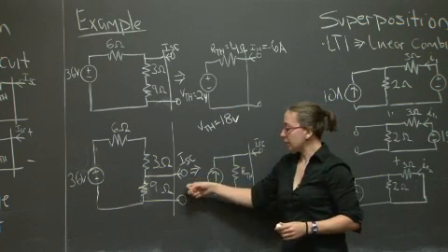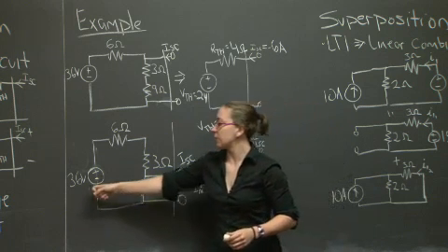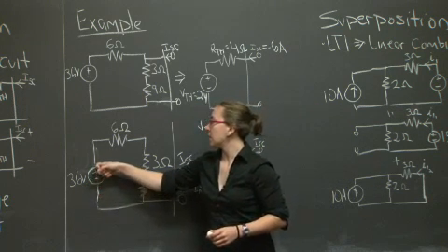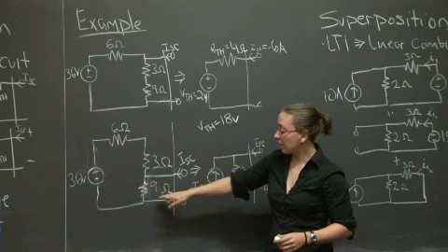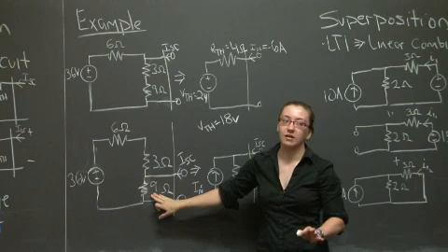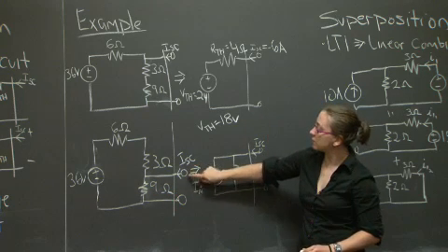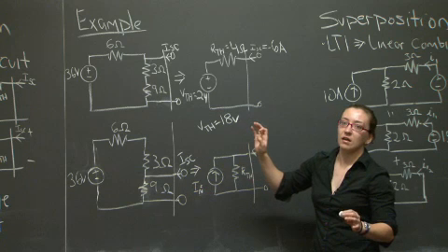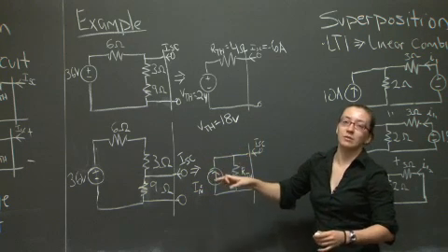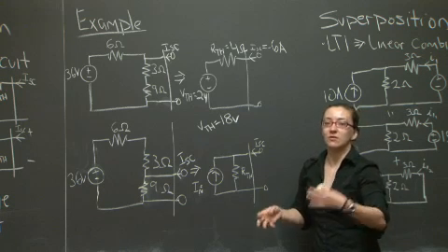The short circuit current associated with connecting these two terminals is 36 volts divided by the sum of these two resistors. Once again, we're going to end up bypassing this resistor entirely because think about it this way. If there was a resistor across here with 0 resistance, all the current would sink through it, or it would represent the location for which infinite current would flow.